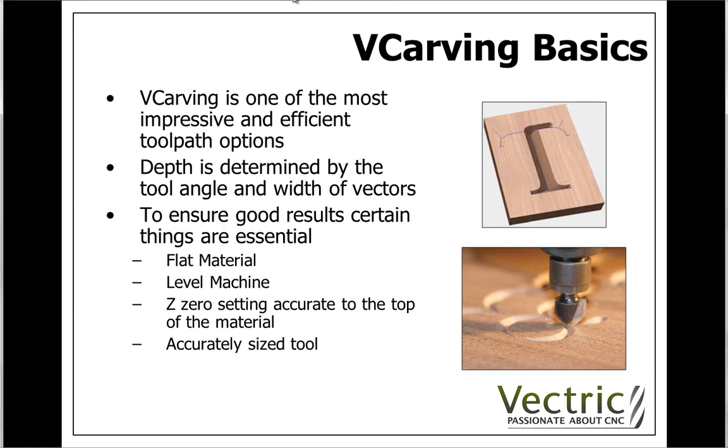Another aspect that's important with regard to the tooling is the fact your tools need to be sharp, and they should end in a point rather than a small flat. You should make sure that the tooling has not got chipped. Any of these things would affect the quality of that point that you're going to get at the bottom of the shape that you're carving.